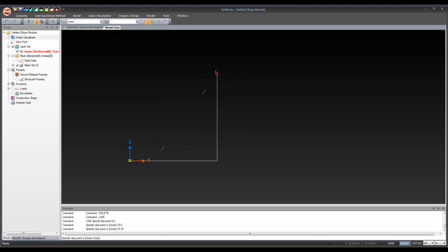Then I can just connect it to make a triangle, and just keep in mind that I have the O-snap option on, which is this option here, which regulates how my lines can connect. For example, I can very easily select that endpoint to connect my lines. And as you can see, when I pull the cursor up, a triangle shows up.